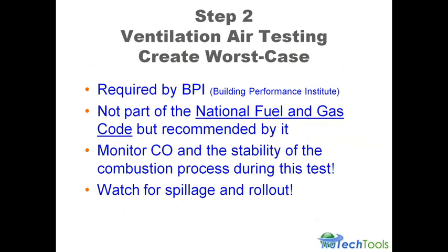Now is when we're going to set up worst case depressurization testing. And this is required by BPI. And if you're an HVAC contractor, this is, I believe, Section D in the appendix of the National Fuel Gas Code. And believe it or not, because it's an appendix of the code, it's recommended by it, but it's not required. But it's still a standard. So you're required to set up worst case conditions. We want to monitor the CO during worst case conditions and the stability of the combustion process during this test. And obviously we want to watch for spillage and rollout.